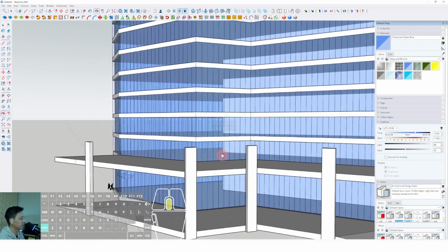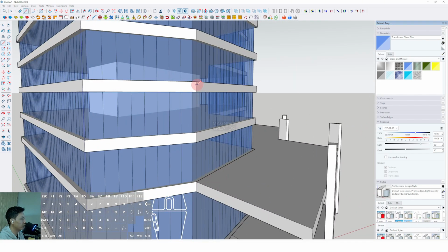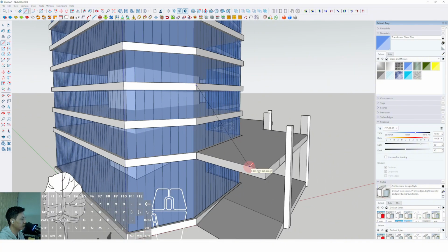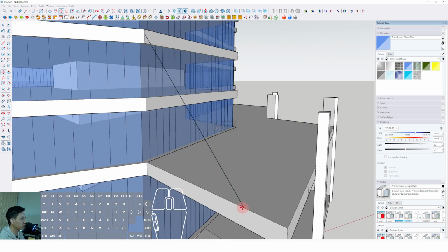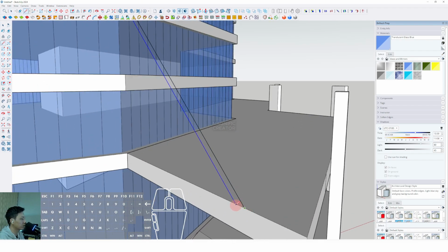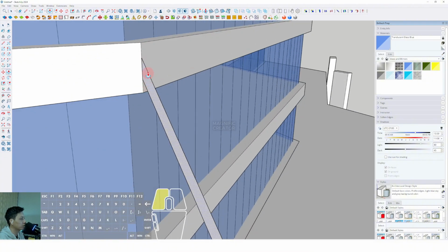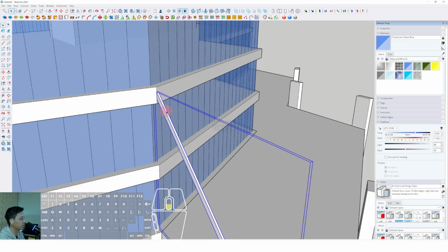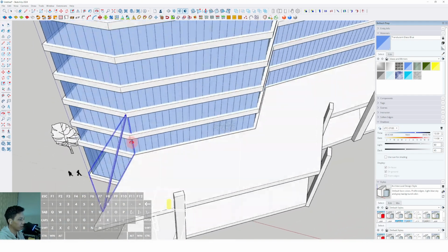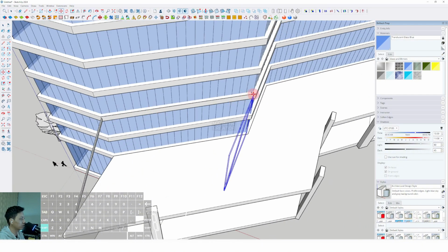And then you can also make another hanging cable in here. You can make the hanging cable in here and click this line, select move, tap control. Okay, you can place it this position, and you can complete the line. Okay, then you can complete the line, triple click, make group, or you can make component, create.